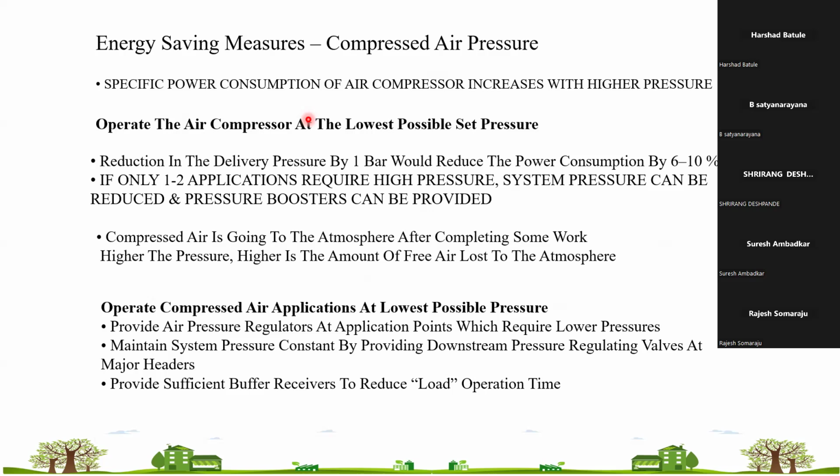Then there is dry air intake. Like the dry air intake example we are seeing, if you are placing your compressor near a cooling tower, you are allowing humid air to pass. So moisture can be carried over to the system, and that will be a hazardous system.